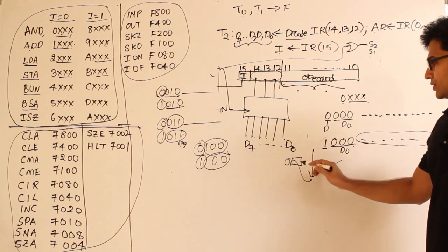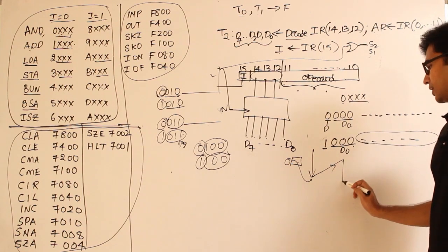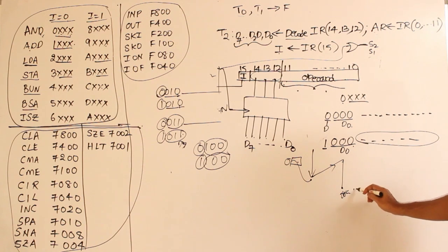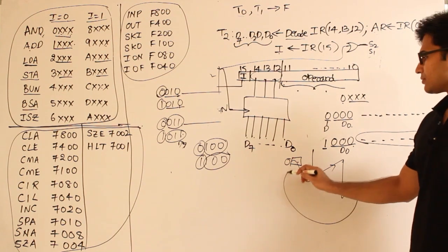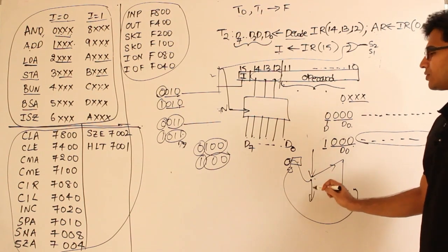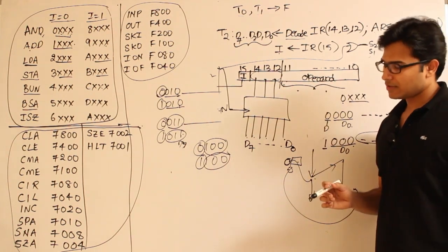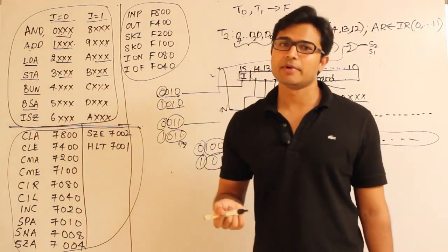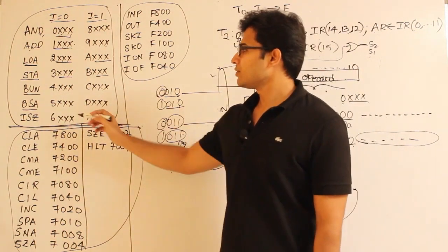Okay, and you save it and then you branch, and after this there will be a return. So this return is going to take the address from location 0 and load it to PC, and it is going to continue. That is why branch and save address is used. Later we shall see the execution and implementation clearly, but now see this one.